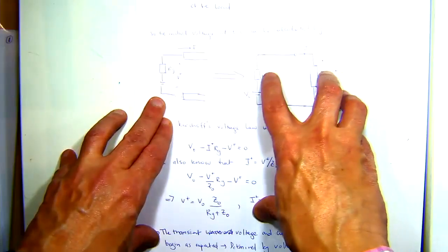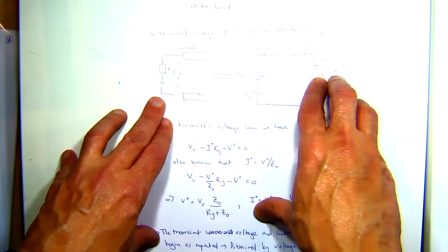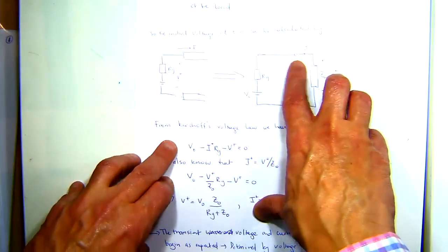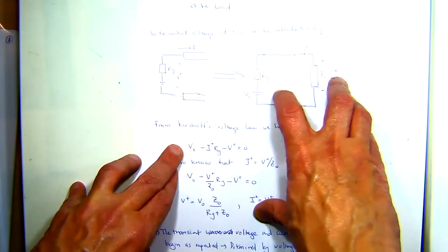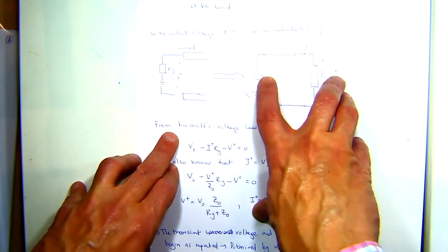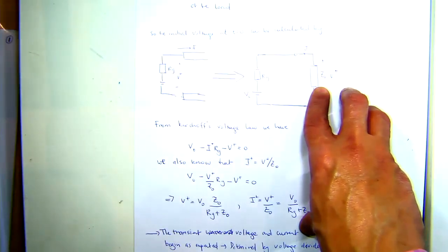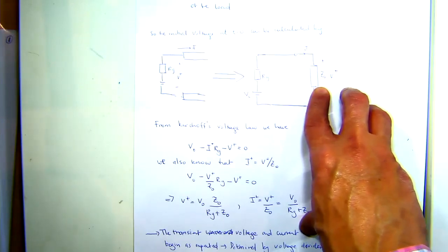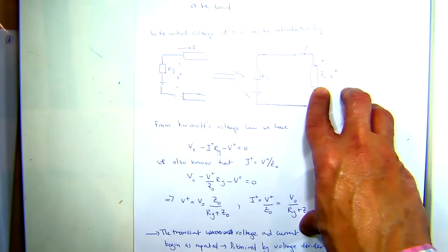That we know in order to work out what the initial forward going voltage wave is going to be is we're going to use a voltage divider. But in this particular case, what we need to do is only focus on the generator impedance and the characteristic impedance of the line. That's the only thing that happens when we've got a transmission line, on that very first instance, when we switch that transmission line in, the wave hasn't actually gone down to the load, so it doesn't actually know what's connected there, right?